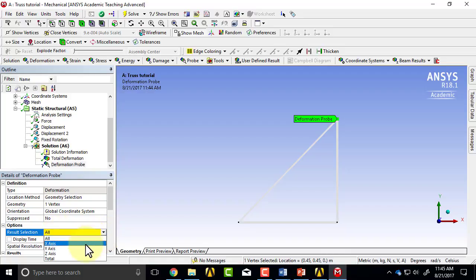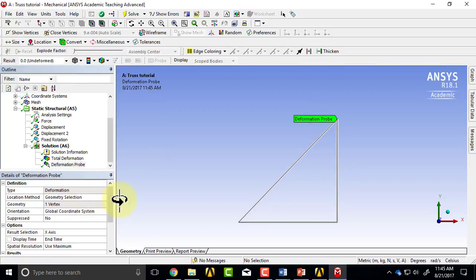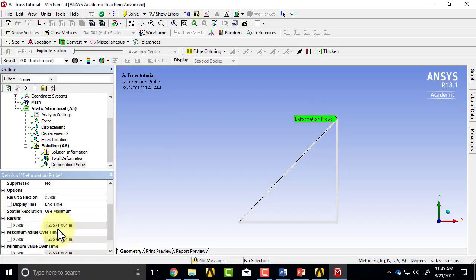That's because you can interrogate only one component at a time. So let's interrogate the X component. Okay. And then once I do that, I should be able to just post-process that. And you might have to expand this, and you see that what that's telling me is that UX, so this is UC X value. This is actually calculated directly from inverting those three algebraic equations. And similarly, you can probe all the other values that are of interest.